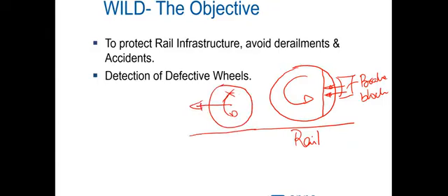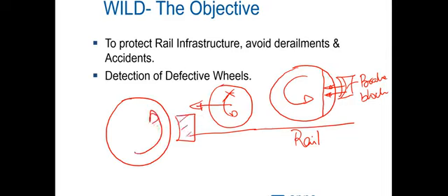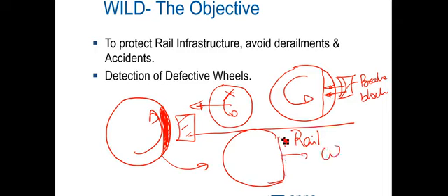So what happens in this case is that this brake block remains fixed and the wheel moves against it, and like you would run a chucky or a grinder, over a period of time this material gets worked out. The net result is that the wheel tends to attain a shape like this. It's no longer circular, it's become flat, and this situation is called a wheel flat. So what causes a wheel flat? Well, it's caused by brake binding.